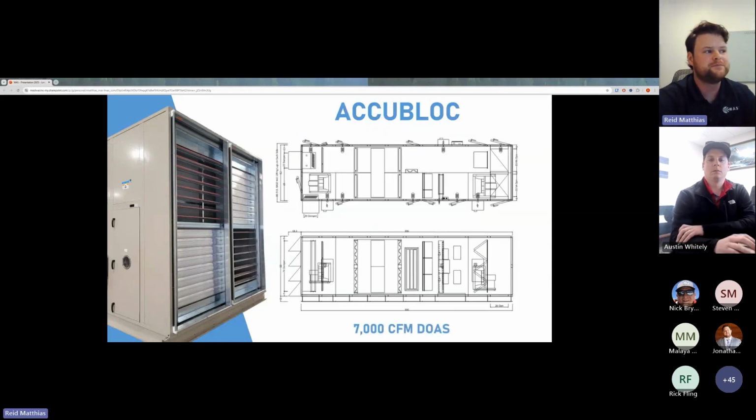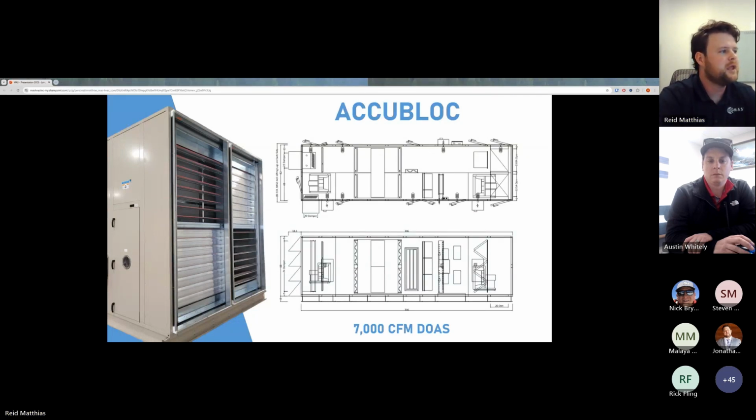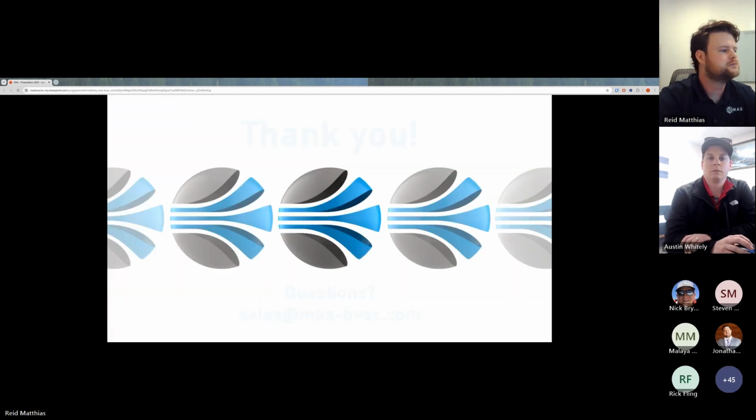Here's an example of it. Layout wise, it works exactly like a plate does, so your airflow crosses with your energy recovery device. But effectiveness wise, it's similar to a wheel, and even more than that. Here, like I said, we just have a heat pump for our additional heating element, which makes it a very efficient unit.